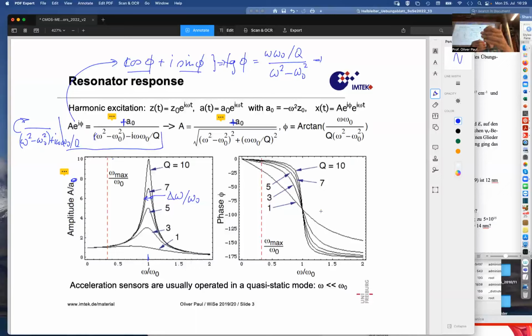You can imagine that if I'm driving an oscillating system at low frequency, so I'm the substrate, and here is M connected to me by the spring. If I do that at low frequency, it is able to follow me. So first of all, the ratio of the motional amplitudes is 1. That's what it says here at low frequencies, 1. And the relative phase is 0.